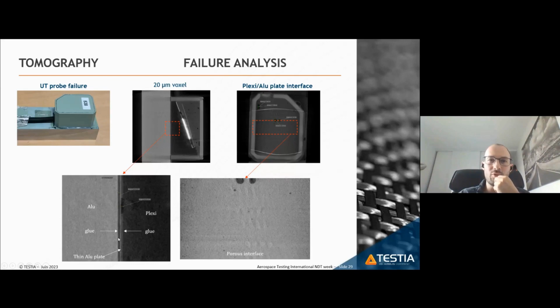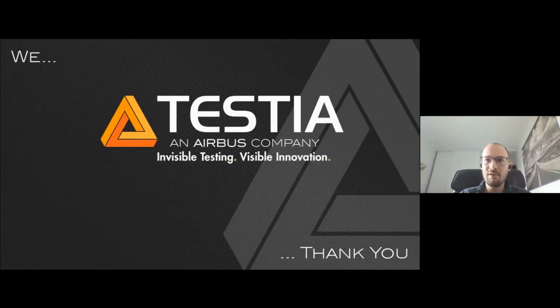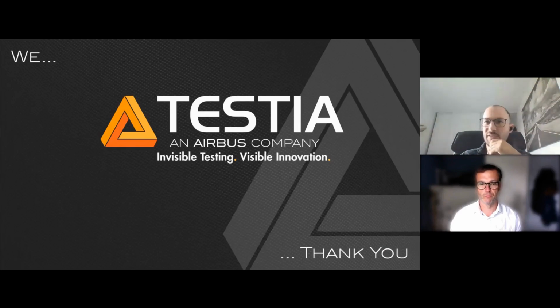And here you have some glue interfaces, and on the glue there were some internal porosity, and also you can observe some delamination between the two interfaces, and that's how we solved that problem. So it can be used also for failure analysis. And I think that's it. I've made every example that we wanted to show.